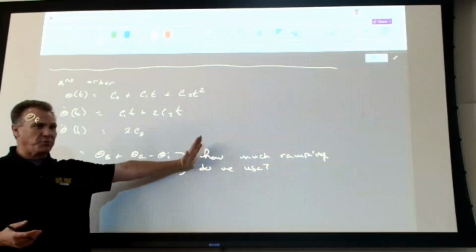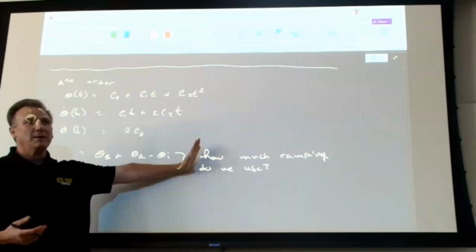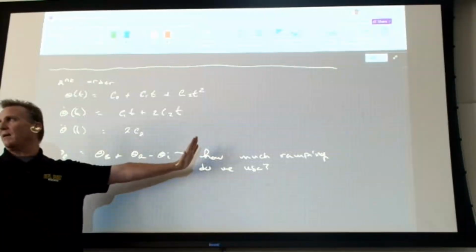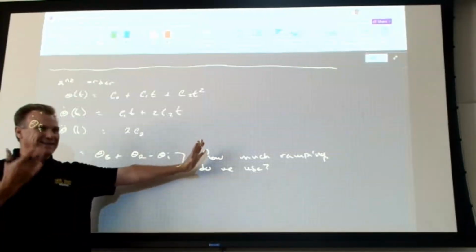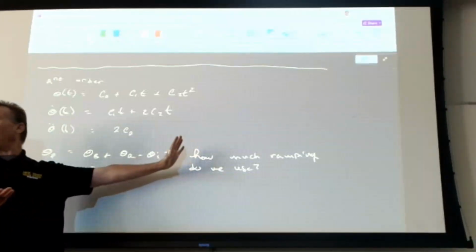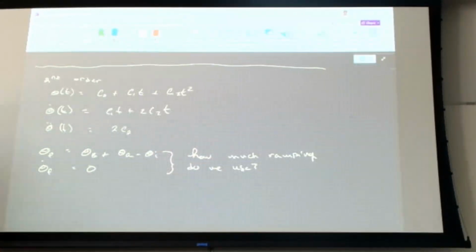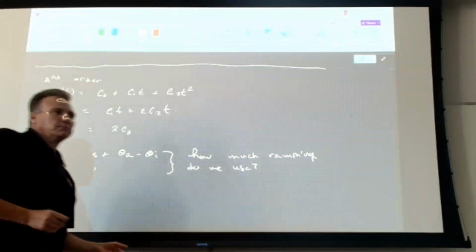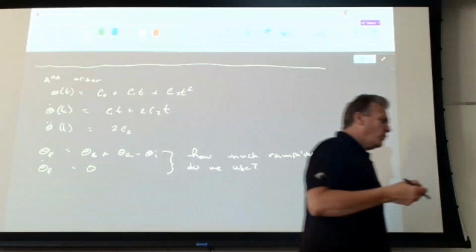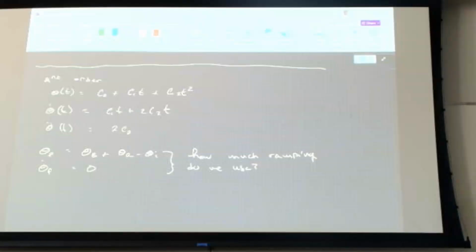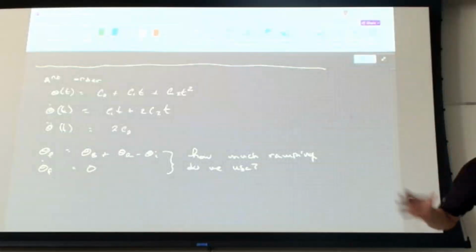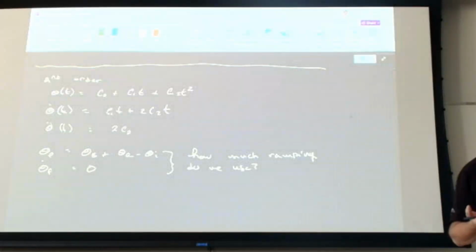Because if you have too much ramping, or if it's too steep, you don't have enough current to drive that, right? Or you don't have enough torque to get what you need out of that motor. And you fail. What could happen if you try to do that in the real world? If my torque requirement exceeds what the motor can provide, what happens to my motor? It stalls. Okay, if it stalls, then what happens if I try to keep driving it once it's stalled?